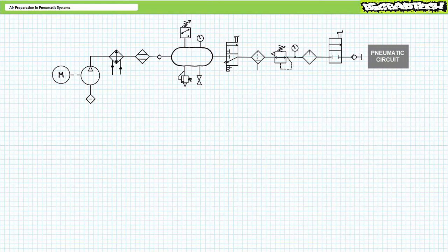This being said, while we've got this complete compressor circuit diagram right in front of us, let's discuss a couple of basic troubleshooting scenarios before we call it a day. Think about the consequences of a tiny leak in the reservoir, a dump valve mistakenly left open, or a safety pressure relief valve that, after experiencing an excess pressure event and venting it to atmosphere, fails to reseat itself properly.